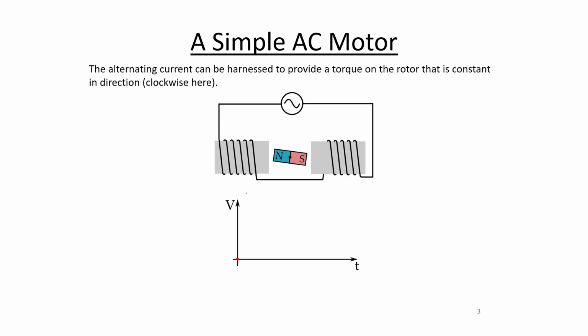And we're going to make our first snapshot of a point where you've got the AC source at this instant in time, you see a little red dot here, just creating 0 volts of difference across the circuit. That, of course, means that 0 current flows in that circuit, and so we wouldn't expect any magnetic field at all, and the rotor would feel no force.